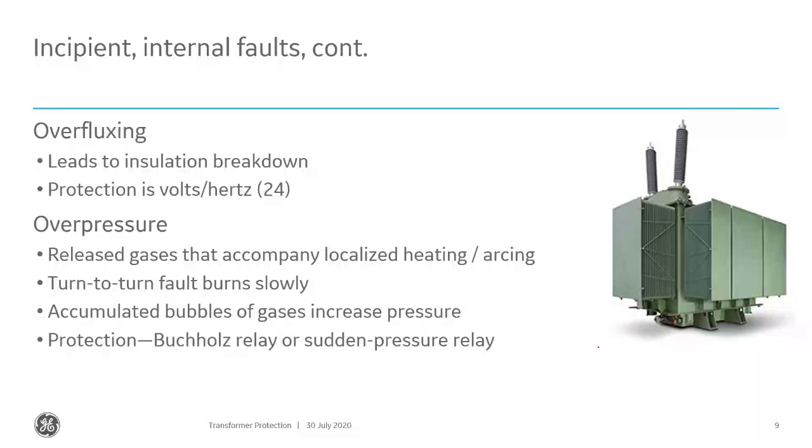Now, the interesting thing about voltage overexcitation, overfluxing, is that because it's damaging the transformer by causing extra heating, it can take some time. So typical settings for that are around 1.1. Typically a transformer is rated for a 10% overexcitation. But we can give it a long time delay before we actually trip because of the mechanism of the failure.